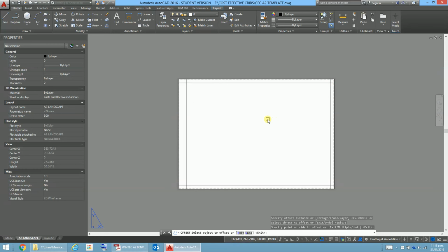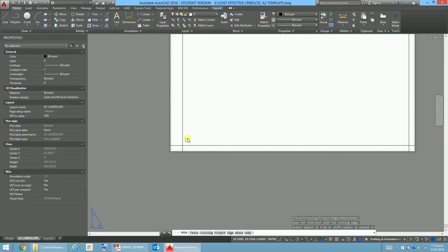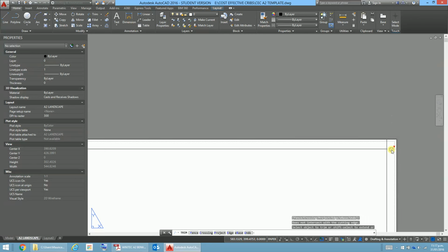Now there's a nice cute little tricky way of doing this. So we just stop that command running, make sure we get back to our full crosshair here, and then we type TR and go enter, enter. So TR with a double tap, enter, enter, and I just click on that one there, click on that one there. Okay, and you can see now that that's just deleting those little bits there. It only deletes between the lines, so sometimes we have to use a different workflow.